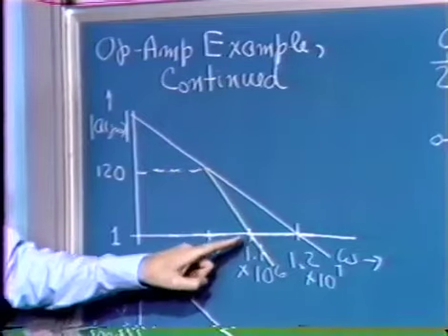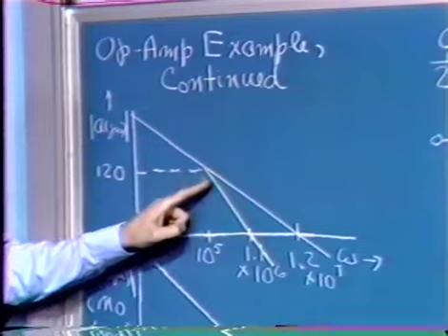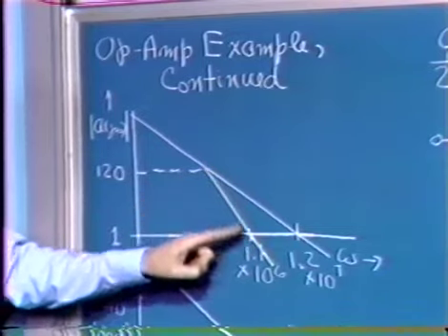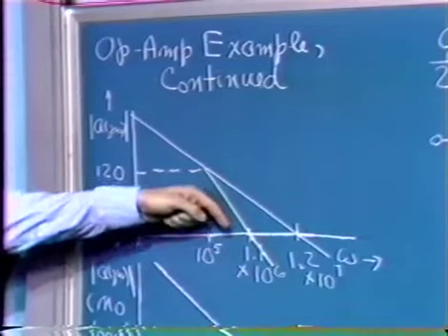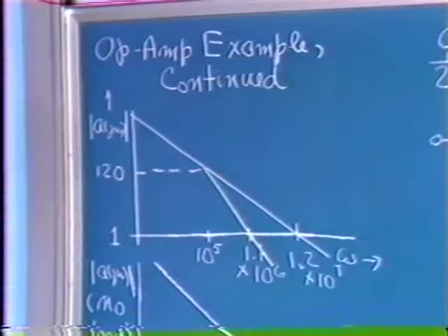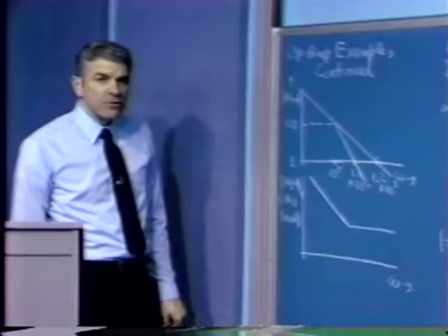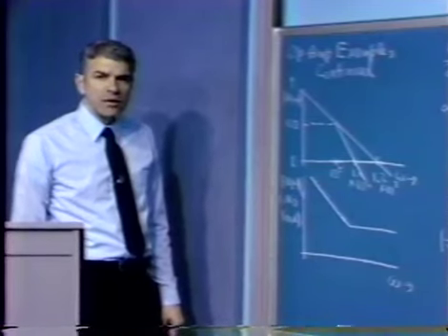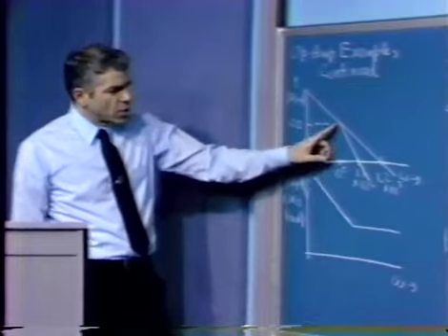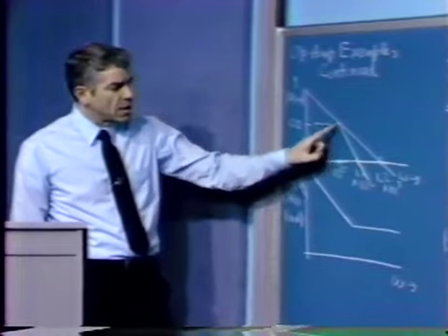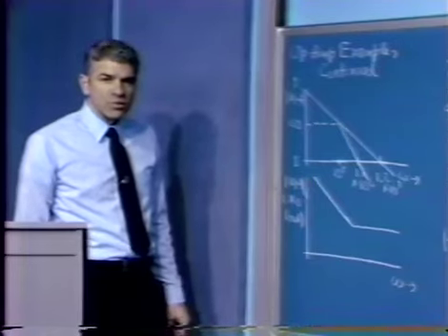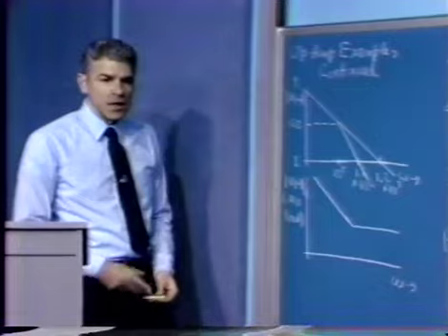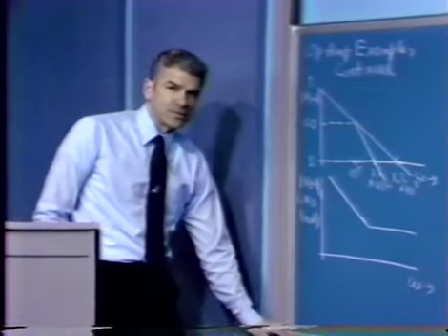Furthermore, notice that we cross over after we've been rolling off as 1 over s squared for about a factor of 10 from this frequency to this one. There's been a long 1 over s squared region, and if you consider the implications of that, we would anticipate a phase margin of somewhere in the order of 1/10 of a radian, roughly 5 degrees, because we're crossing over a factor of 10 beyond the second pole. We'd certainly expect that that sort of phase margin would result in very marginally stable performance, and that's what we see in the step response.